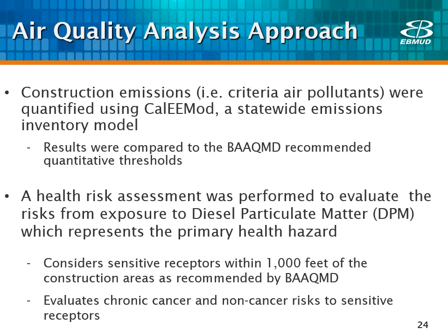Also, a health risk assessment was performed to evaluate the risks from exposure to diesel particulate matter, DPM, which represents the primary health risk, to sensitive residential receptors, including infants, children, and adults. The health risk assessment considers sensitive receptors within 1,000 feet of the construction areas as recommended by BAAQMD and evaluates chronic cancer and non-cancer risks to sensitive receptors.